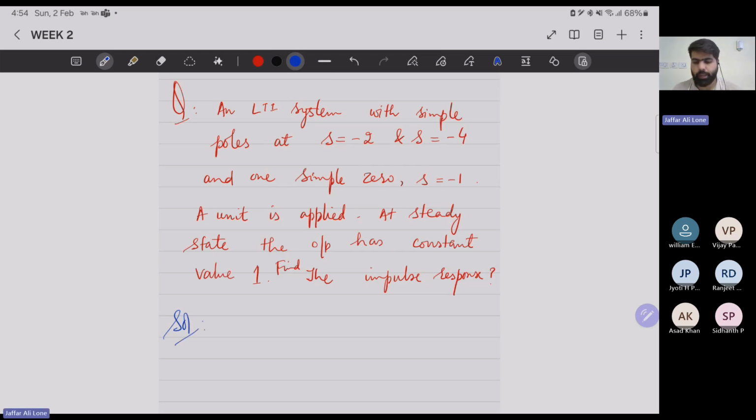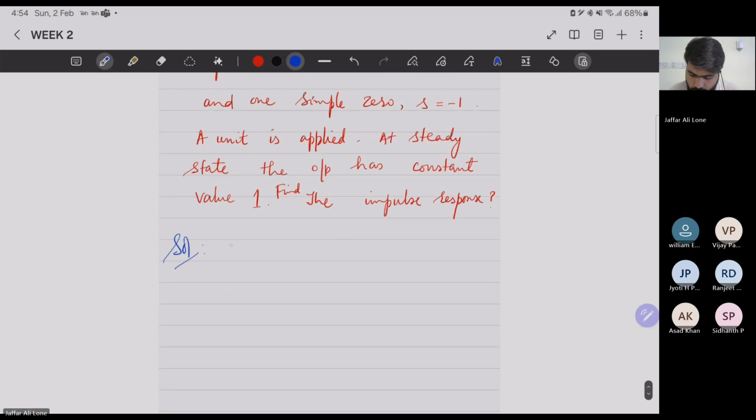This was taught in the lectures, but I have not revised it. So quickly, if I have to revise it: the transfer function is the Laplace transform of the output over the Laplace transform of the input, given all the initial conditions are zero. Now, if you give this R(s) as the input, in the time domain, let's assume this r(t) we give as an impulse function.